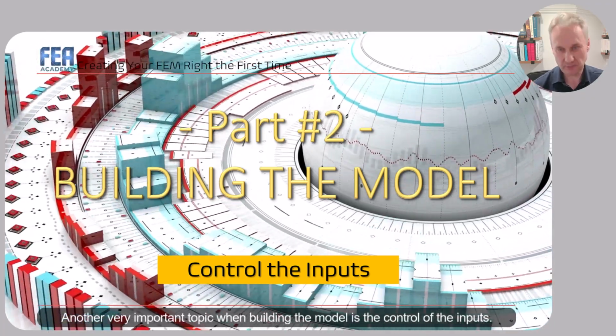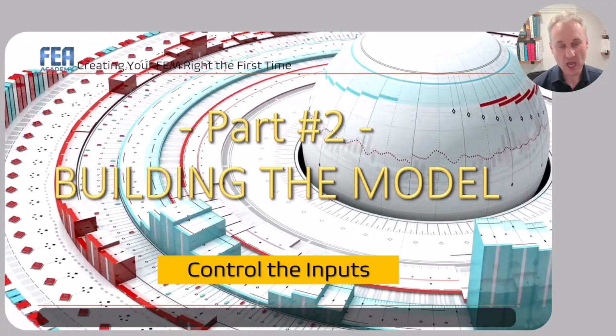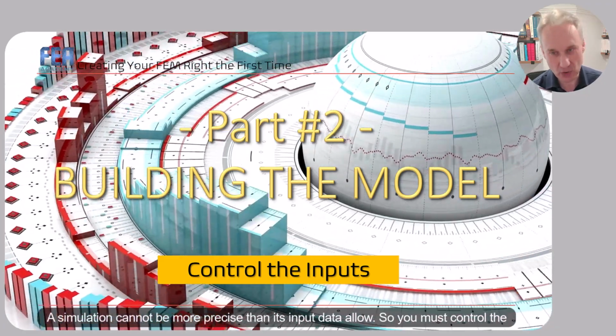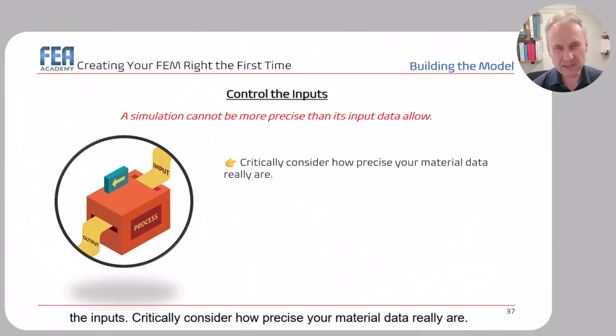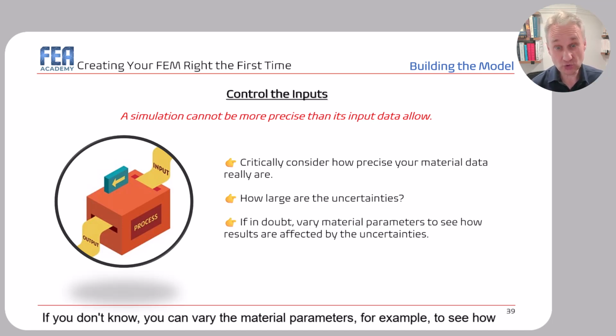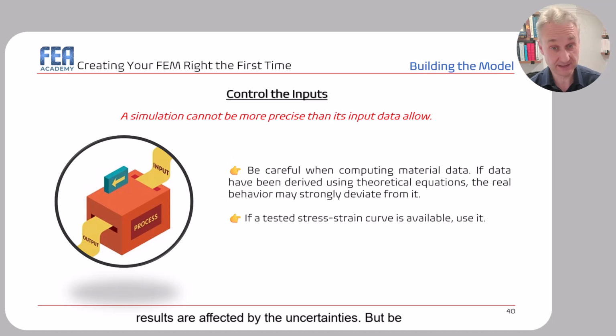Another very important topic when building the model is the control of the inputs. A simulation cannot be more precise than its input data allow, so you must control the inputs. Critically consider how precise your material data really are. How large are the uncertainties? If you don't know, you can vary the material parameters, for example, to see how results are affected by the uncertainties.